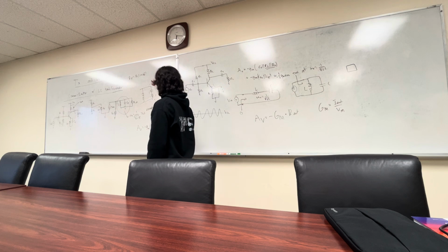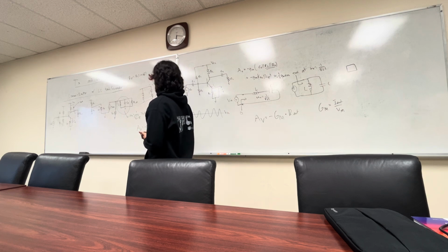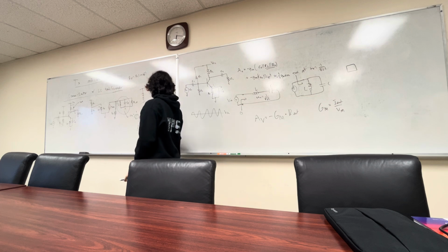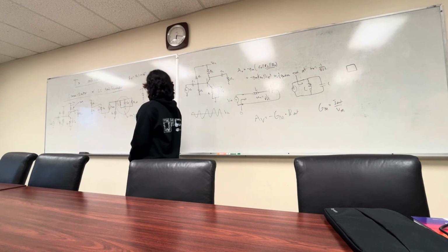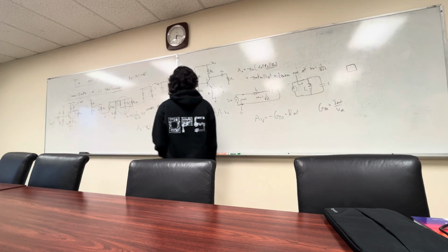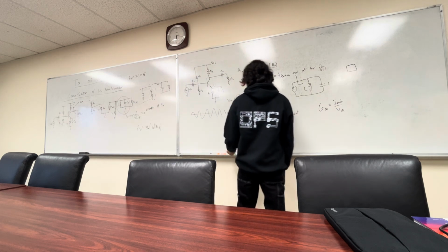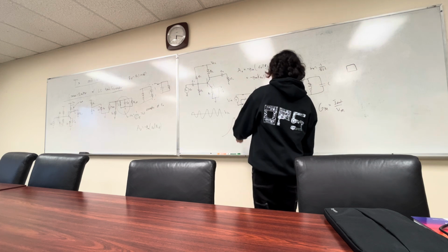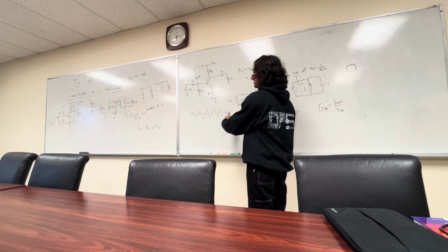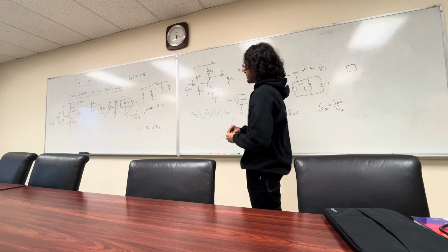Again, Q is like 10 and RS is like 50. We typically don't like inductors, but for this reason, we do like them because they create a very sharp response if you look at the impedance at our collector, and we like having this because of all the frequencies we don't amplify.